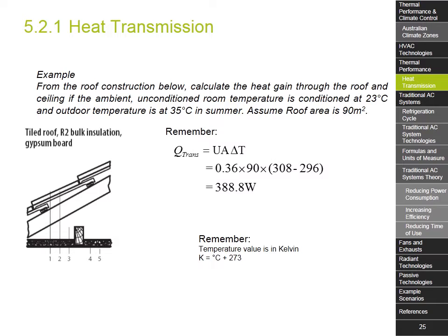What is important to understand here is that the internal thermal performance of a space is significantly affected by the resistance value of the materials used to enclose it. The higher the resistance, the less temperature fluctuation, and the easier it is to condition the space, which, at the end of the day, means less energy used in cooling or heating.